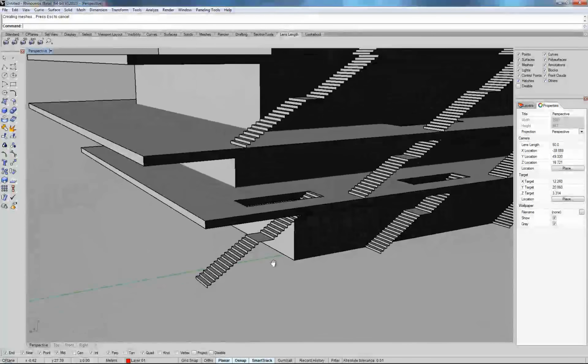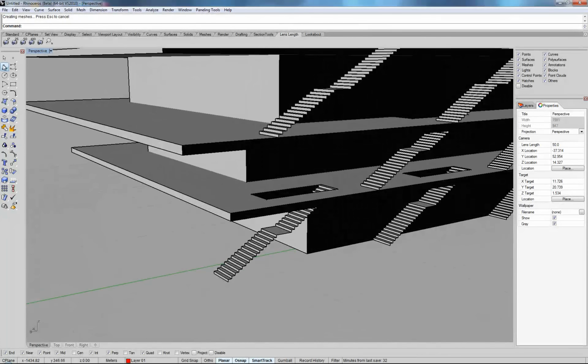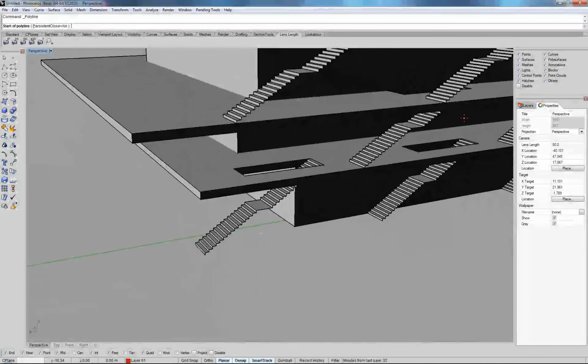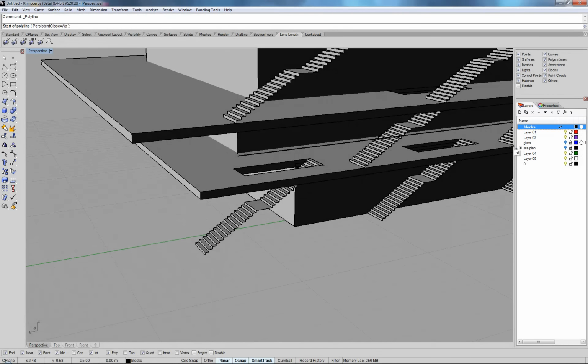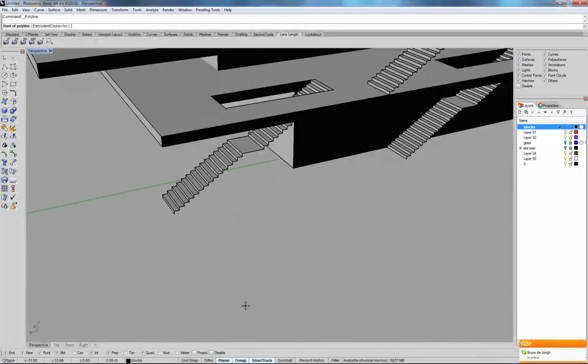Okay, so to make a stair, it's very simple. Usually you should use a set of references. I start with the normal C-plane. Let's go to the blocks, and I'll make a line, then I click Shift so that the line sticks to one of the axes, for instance X and Y. It's an ortho mode, and then I click the Tab key. The Tab key will lock the line in this direction, and this is very useful also if you're working to an angle. If I click Tab again, this becomes free.